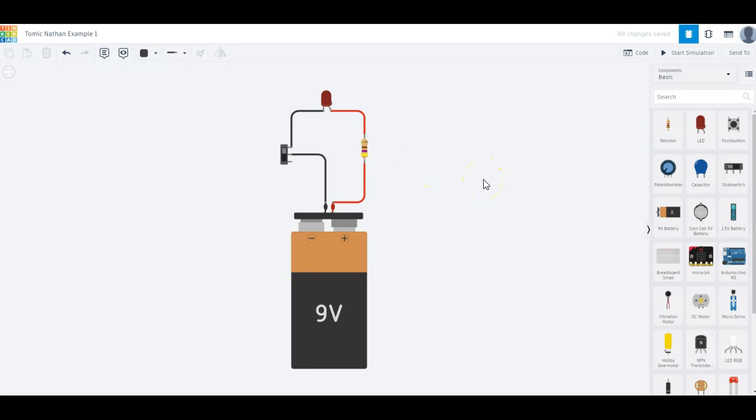And the final thing that I would like to show you is adding notes to your designs. So up here next to the colors, we have these two icons. If you click on this one here, this is the notes tool. You can also use the shortcut key of N to put a note in. So it's a little reminder, and you can type a note in here. So this is the first circuit. Okay, you can have as much text as you like, because you can then press the little takeaway sign here to sort of collapse it, and anytime you click on it, it will open up to show you.